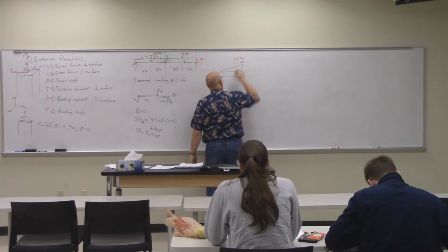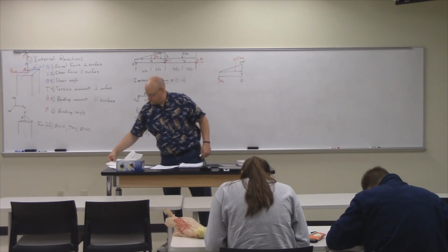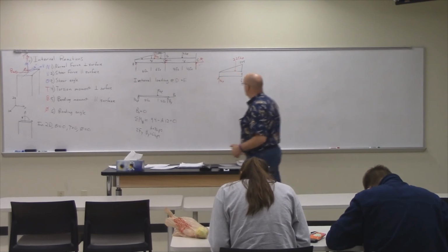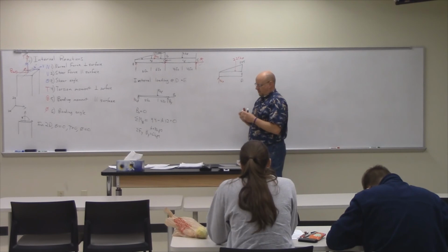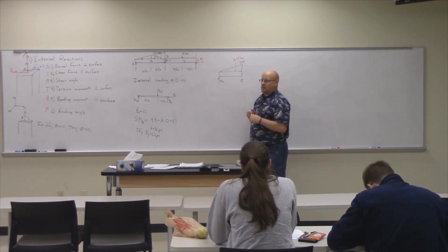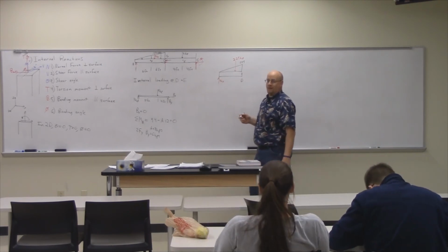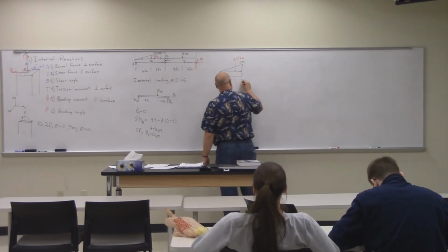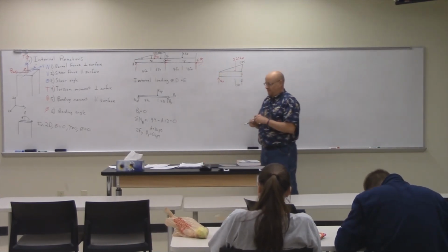So I have 2.25 kips pushing down there. Make sure I didn't lie to you. Okay, mental math. Where is that located? Where is that pushing down? How far from D? 1/3 times 6, yes. 2 feet. And so now I can do all the work.